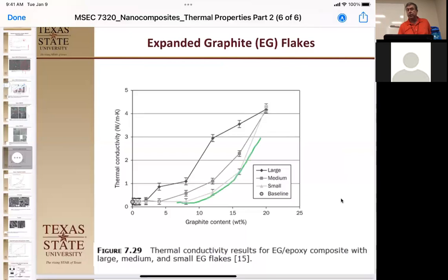The smaller plates have the lower persistence length. The medium plates are better, but we have a nice sharp turn on here. And this probably, if they did a few more points, they would have gotten a nicer curve. So we're looking at different ways to get different kinds of thermal conductivity here. And choosing your filler and choosing your polymer, depending on whether you want a biaxial transfer or just a uniaxial transfer, you can pick your material and or your alignment technique.